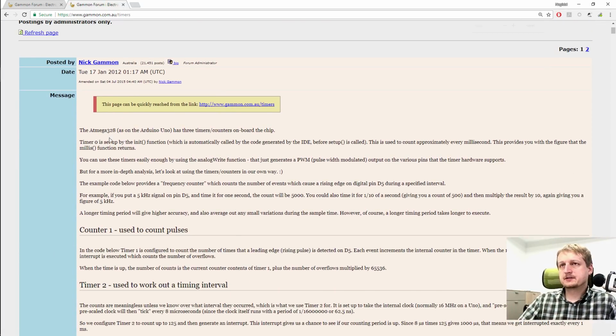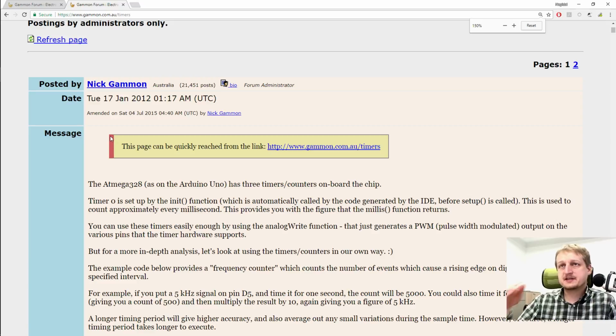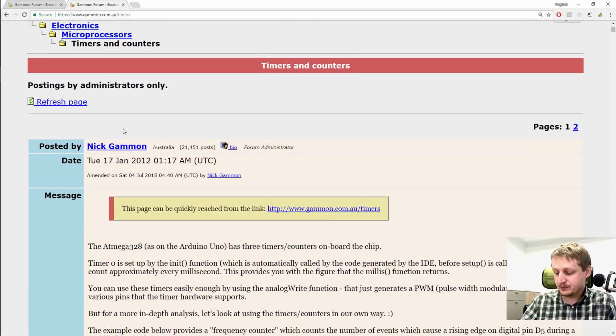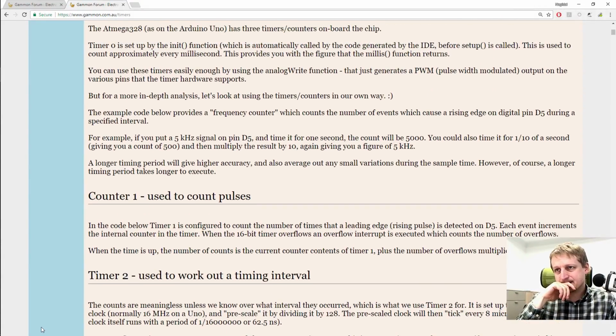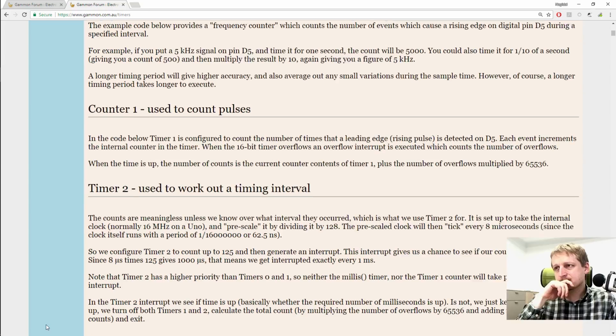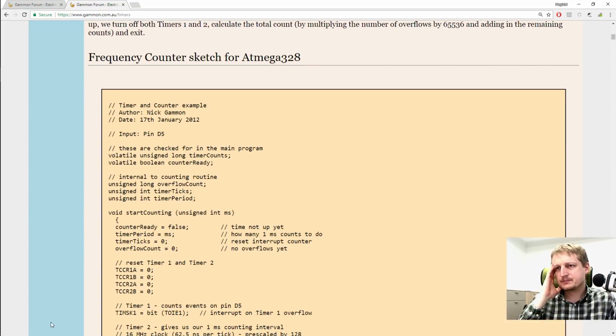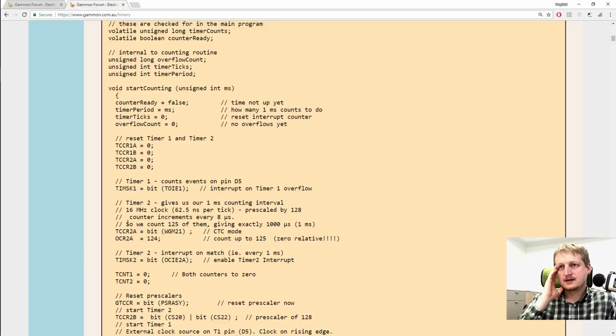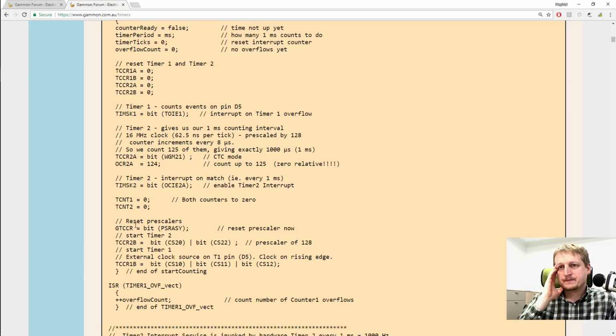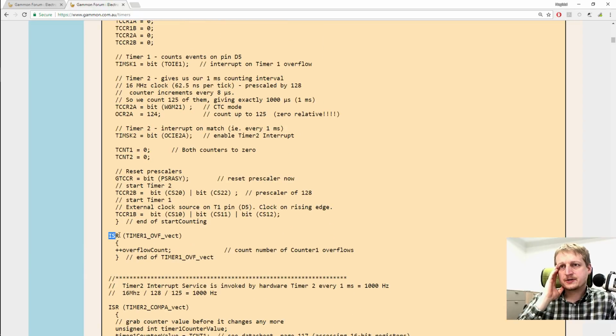I actually started reading this thing because we need a timer for our RPM meter, and he goes really to low-level interrupt programming, and he's got some processor internal variables here, and instead of attachInterrupt, he is using this ISR function.